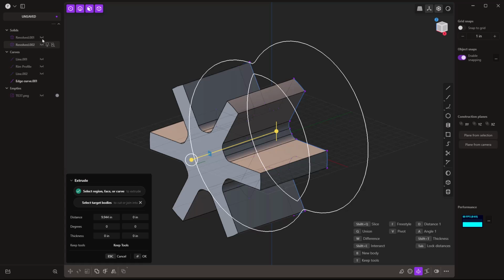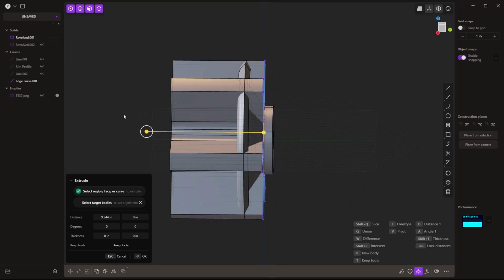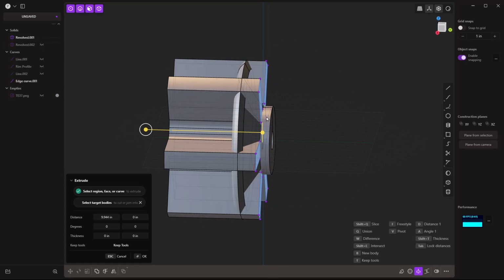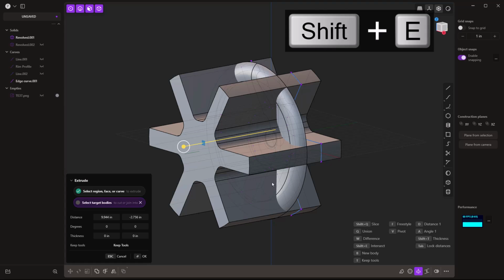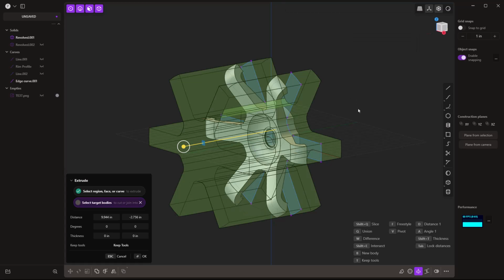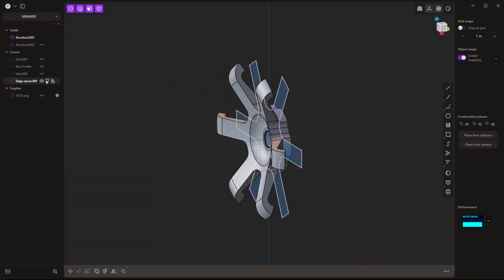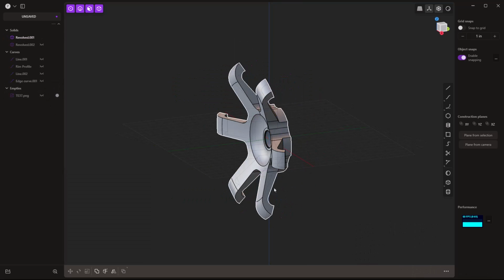Pull this forward. We're going to show that spoke. Notice that there is some overlap in the back, so I want to take the back side, back that direction, Shift and E, and then select the revolve spoke section. So basically what intersect is going to do, it's going to take the solid extrude that we just created, and wherever it overlaps that other revolved surface, it's going to basically create that for us. So right click to accept, and then we can hide that edge curve.